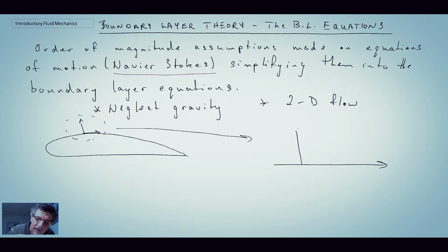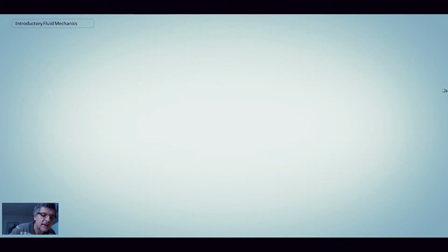And we're going to consider a section normal to the wall. So X is going to be in the wall direction, and we're going to examine the boundary layer in this region. Outside of that would be the free stream flow. But this is going to be the velocity profile, and it will be a function of both position in the X direction as well as normal to the wall in the Y direction.